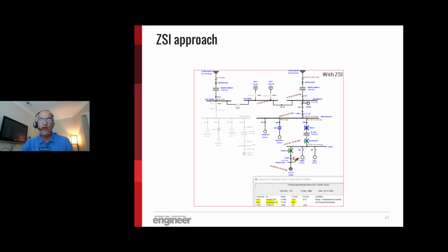Keep in mind that our incoming circuit breaker instantaneous is enabled, but if there is a fault at the terminal of that feeder, as you see here, this is the sequence of operation. My feeder breaker will still go down first, then my incoming breaker, and of course the primary protection, which is the right sequence of events.